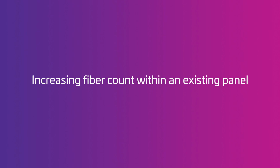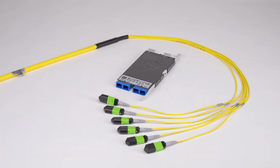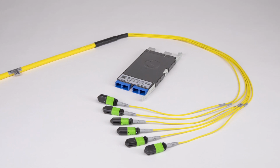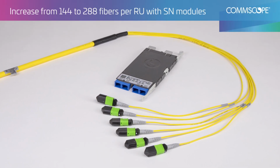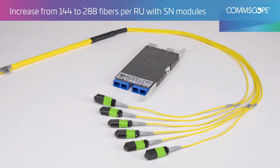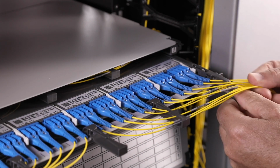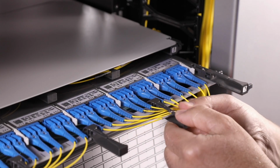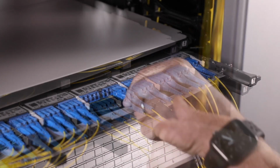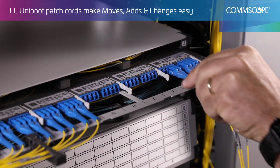What if you want to do something a little more involved, like increasing your fiber count within the panel? With Propel, if you're already using MPO 8 or MPO 16 single-mode trunks to LC duplex, you can go from 144 fibers to 288 per rack unit by just replacing the LC modules with SN modules. Take the patch cords out of the clips and remove the clips. Disconnect the LC patch cords from the MPO 8 modules.